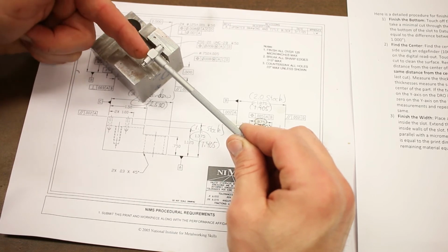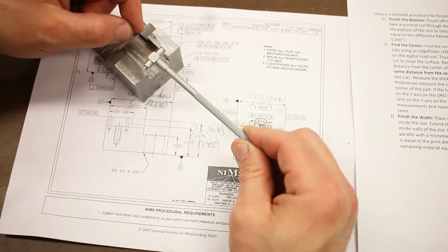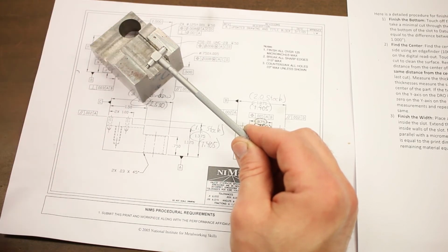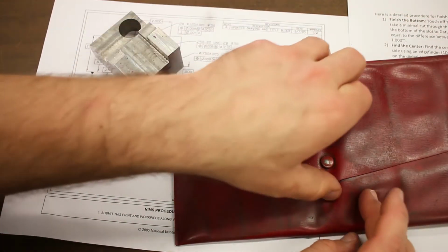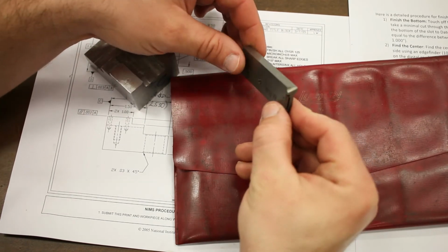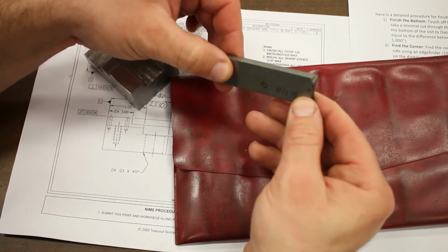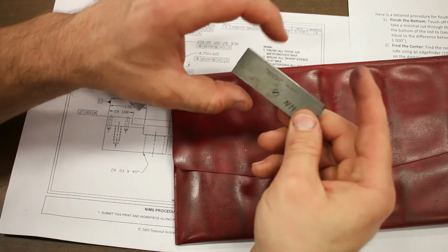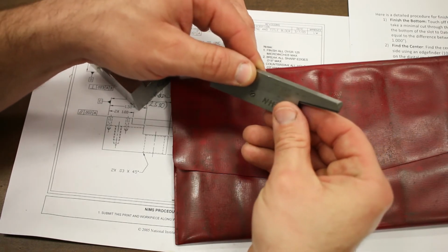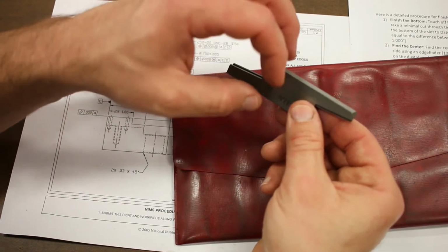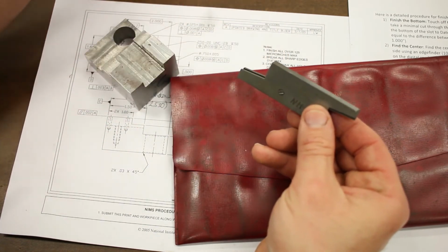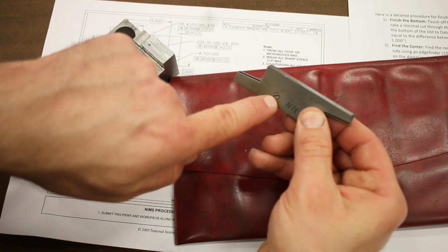We just need to take something that takes this basic principle of turning an innie into an outie, but something that stays square to flat surfaces. And that's where these come in. These are adjustable parallels. These are two wedges which ride in a dovetail slide, and these two surfaces on the outside are very, very parallel to each other, no matter what position you set them in. But you can see that because they're on this tapered slideway, you can actually change the distance across them. You can also lock them in position with this screw right here.